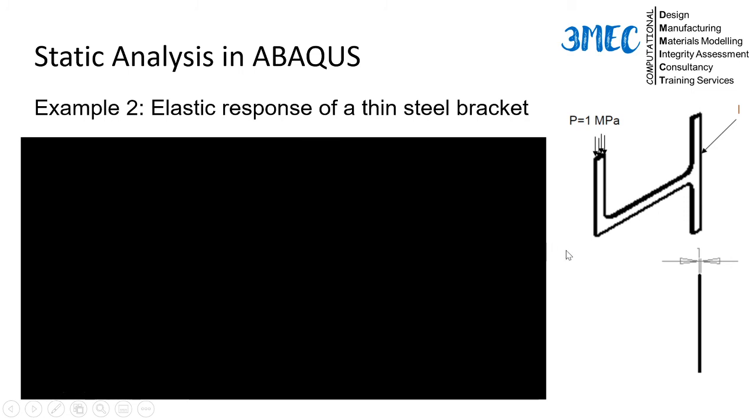So hope it makes sense now how to perform analysis in 2D. So as I told you, in reality, you can also reduce your 3D problem to 2D problem. And as I gave you an example that for the previous case, for thick bracket, you can use a plane strain case, and for thin brackets, as a thumb rule, you can use plane stress case if loads and geometries are symmetric.